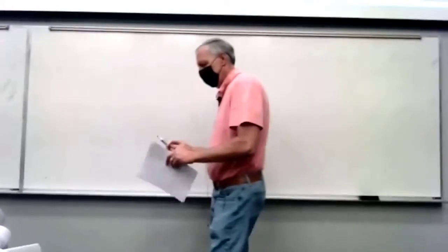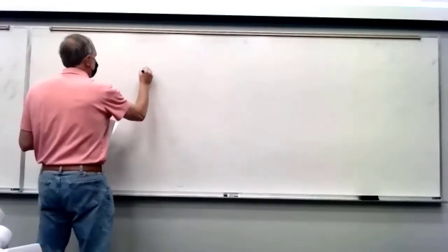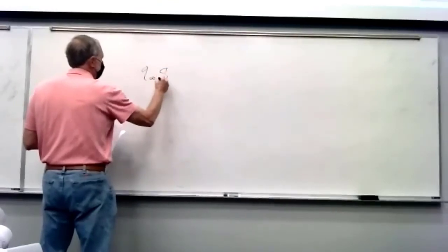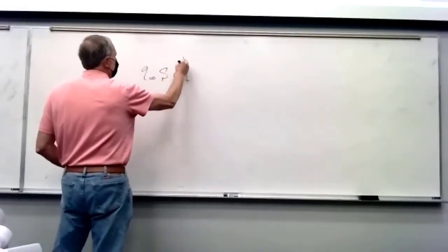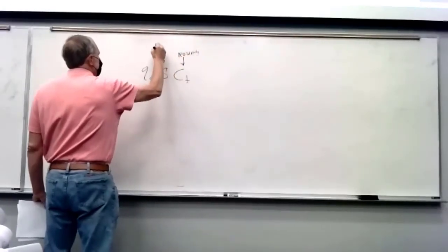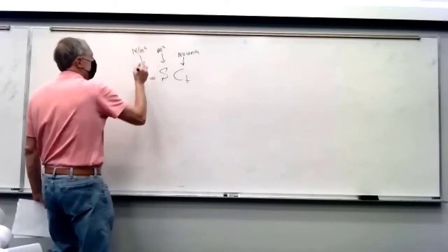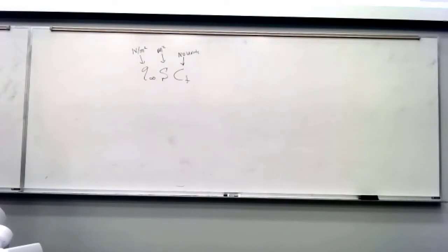What are the units on our total drag? What does it look like? Let's see, that's metric, right? So it'll be newtons. Oh, so it's a force. Yeah. And if you look at the units, it's q infinity times S times CF, right? There's no units on CF. This is meters squared, and this is newtons per meter squared. But yeah, drag is a force, lift is a force.